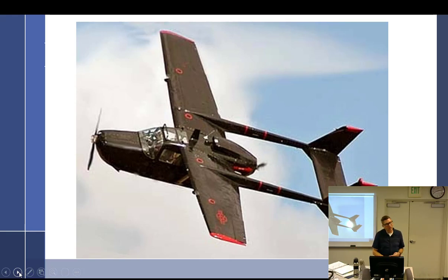But no, I like the Skymasters. Even as a mechanic, I think they're cool. They're a pain in the butt to work on. They've got some serious issues. One of the problems I feel with them is that they're only running Lycoming IO-360s, which is, I don't know, what, 160-some horsepower? And so that's a big plane to be running around on 160 horsepower.